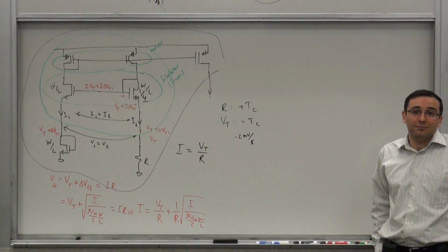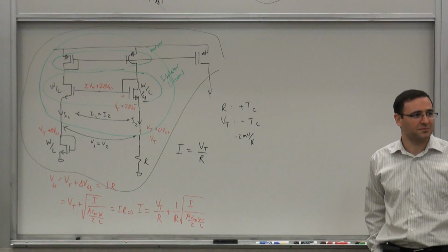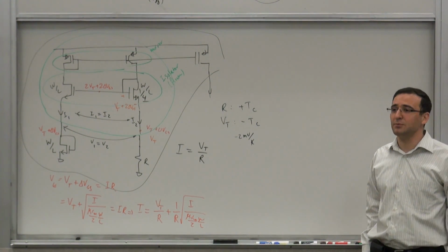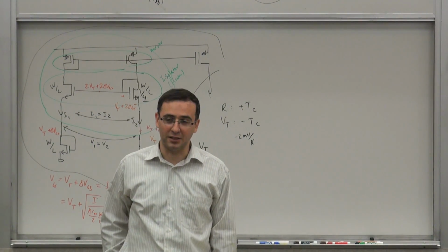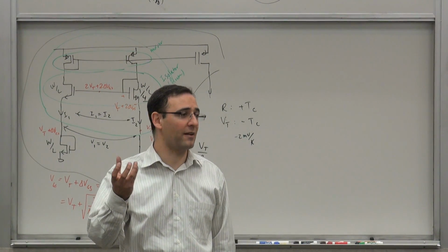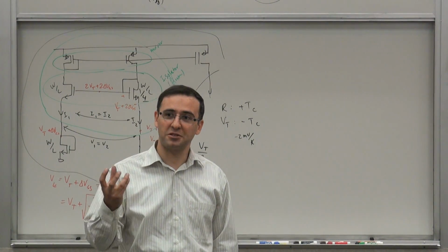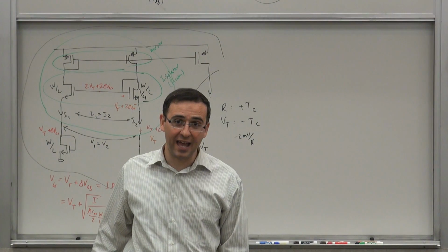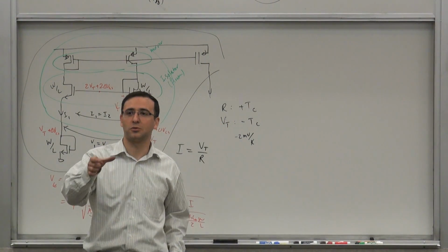Anyway, there are examples where you may not worry too much about it because the temperature is controlled by some other mechanism. Sometimes you're so sensitive to variations that you do everything, but still you don't get the stability that you need. So you make these references, for instance frequency references called the oven control crystal. They make this crystal as temperature independent as they can, and then still they want to make it so stable they put it in a temperature controlled oven.